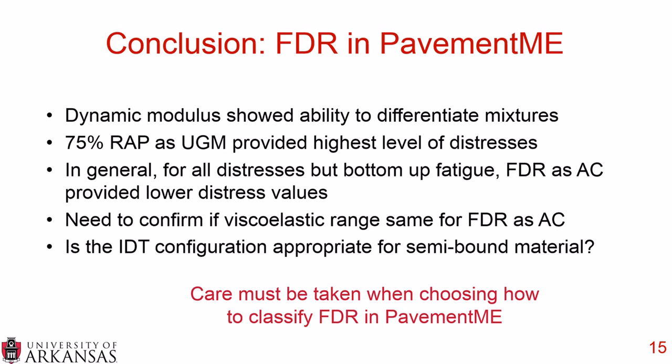I think this could be expanded also into CIR, or cold in-place recycling, and perhaps HIR, hot in-place recycling. And I think this just shows the challenges with taking these semi-bound materials and asking, well, how do they behave? They don't behave like an unbound material, and they don't behave like a fully bound material either. And so I think there's a lot of work that could be done in better understanding and better classifying this material in PavementME.